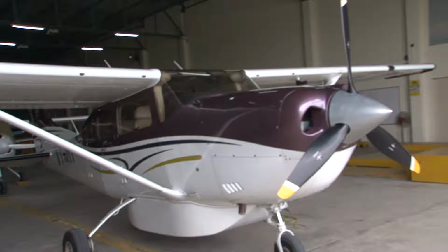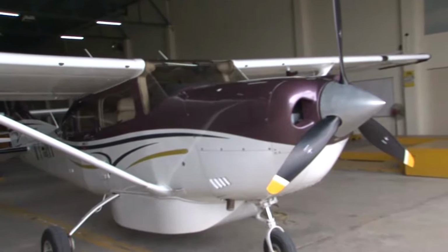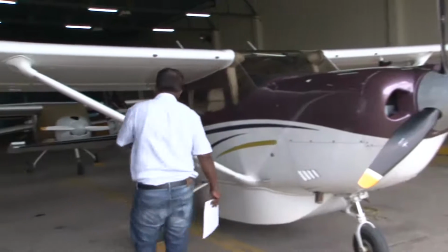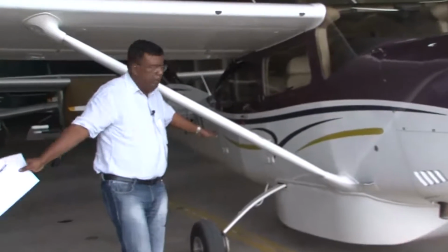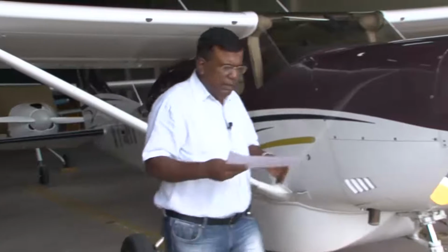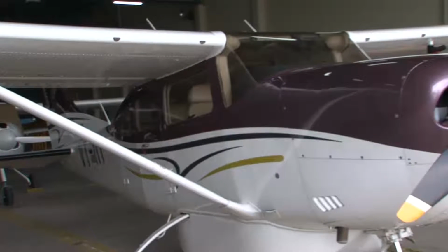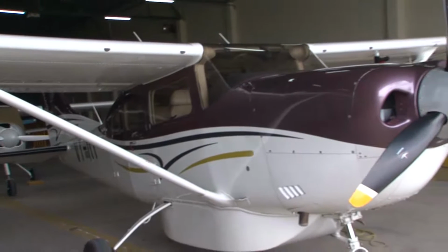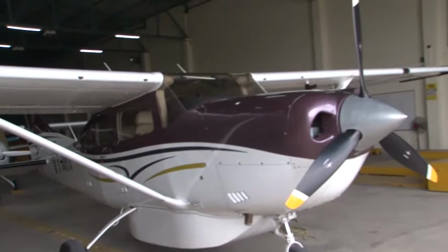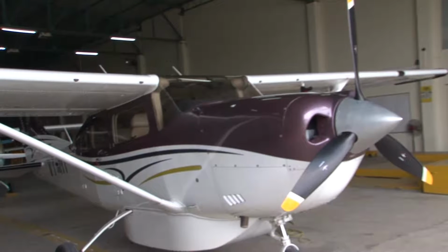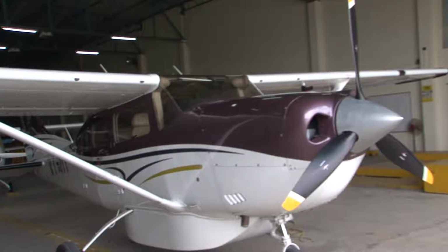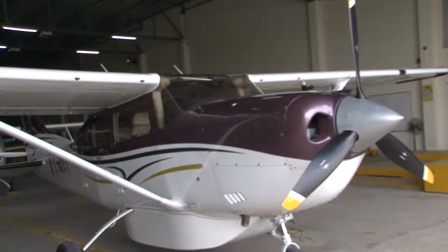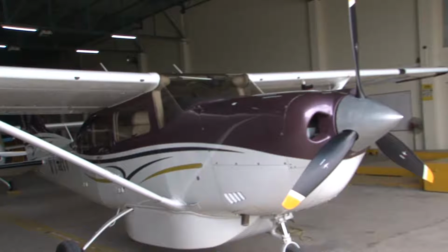Now from here, I need to see also the landing gears. If you see, these are the rear landing gear. So I would like to know what the wheelbase is as a conceptual person. I am now doing conceptual design, and the wheelbase, as per my record, is around 5.77 feet. You can understand if the wheelbase is less than a threshold, the aircraft can topple like this, right? If it is more, it is also not going to help you. So there is an optimal value you find out as a designer. Again, you use some statistical data which has evolved for different weight classes, different types of wing.